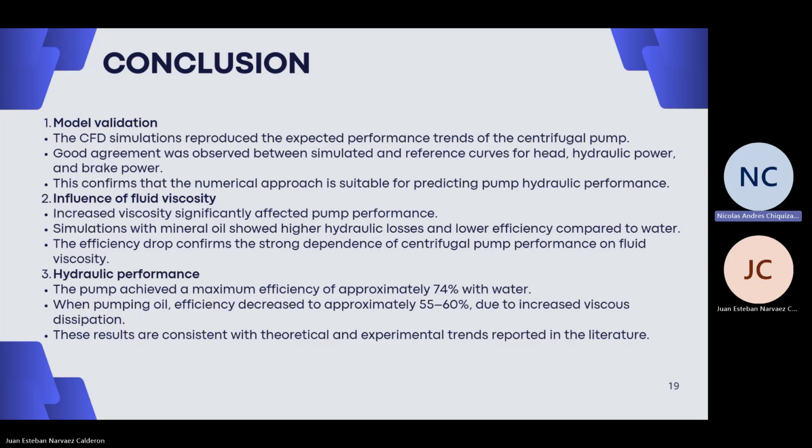The study also demonstrated that the fluid viscosity significantly affected pump performance, reducing efficiency due to the higher viscous losses. The maximum efficiency obtained was approximately 74 percent with water, while efficiency decreased to around 55 to 60 percent with mineral oil. Overall, the results show CFD is a powerful tool for analyzing and optimizing centrifugal pump design.